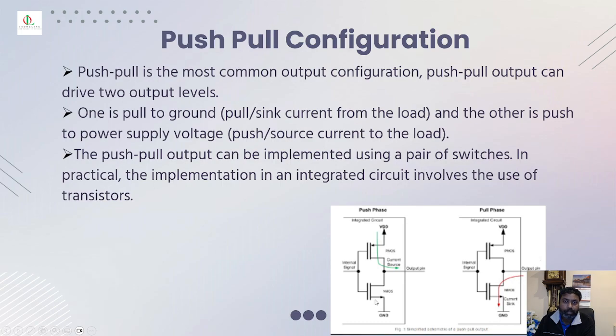If you know CMOS theory, then you would follow me with this. NMOS will be active low, in other words it will be off, so the VDD voltage will go out to the output pin straight away, whatever the VDD is. So that's the push.